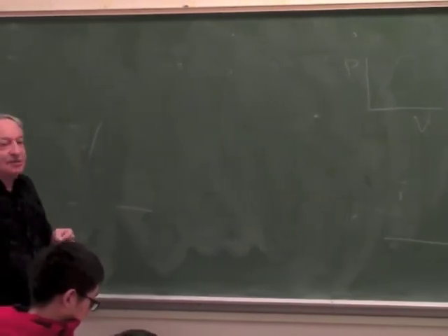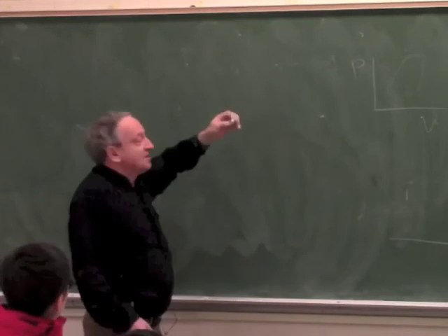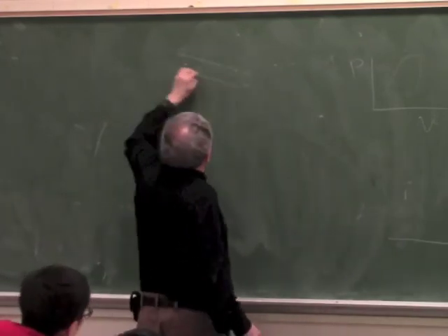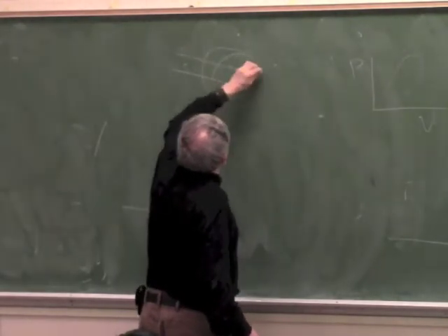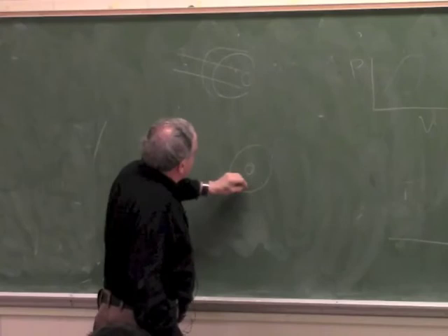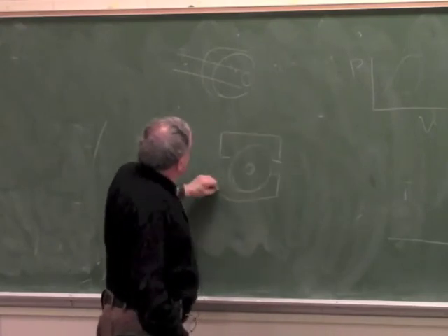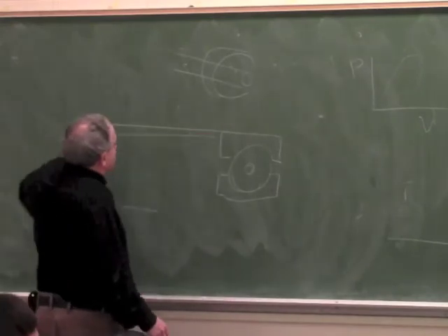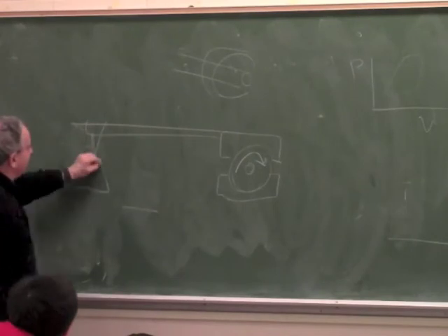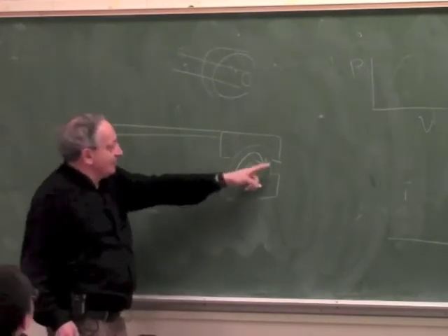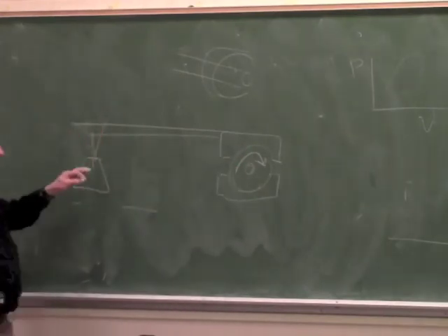So how did they do it in the old days? So in the old days, the typical thing was there was a motor. The motor was actually a steam engine, but it doesn't matter. There was a shaft. You put a pulley on it, okay, and you put a brake. I draw it from here. This is a pulley, and you put an actual wooden brake on the pulley, and let's say the motor was turning this way, and you put a weight. You put a weight here, and this slipped. You tightened the brake, and you let the motor slip until it balanced.